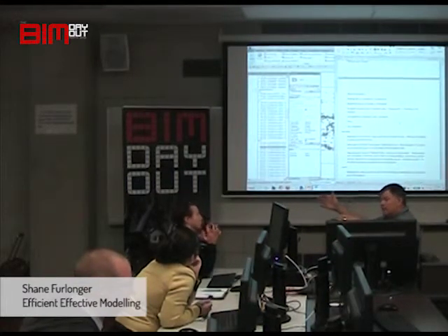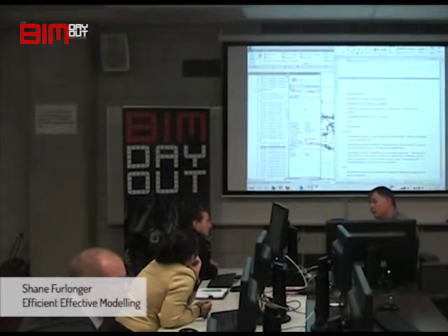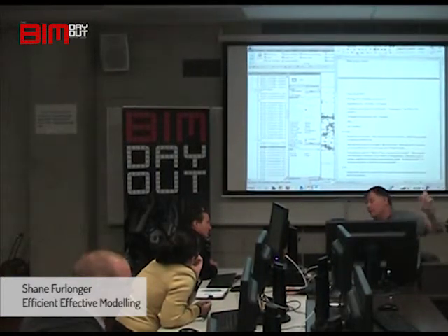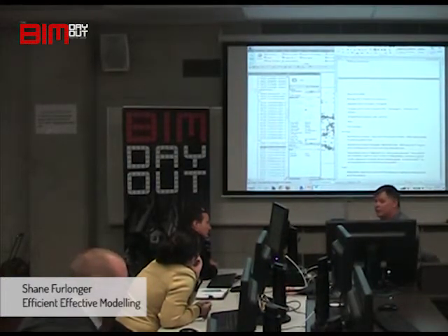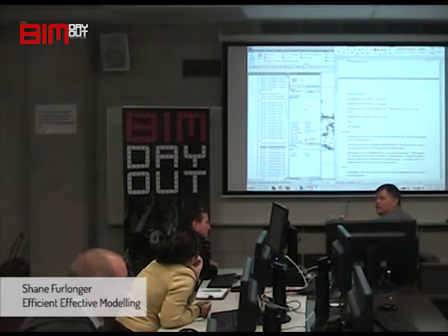So if you do it in the legend view, like I said, create a group, which makes sense as well. If that window appears 20 times on the building, you only have to do it once, and then you copy that group around the building. So you just make an instance of that group around the whole building. You only have to change it once.